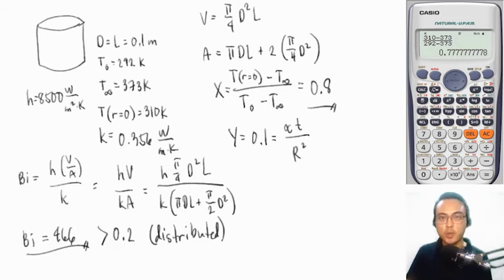In your exams, you have to look for the values of the thermal conductivity, density, and heat capacity of concrete. But for illustration purposes in this example, we have a value of alpha, and that is 5.95 times 10 raised to negative 7 square meter per second. If you substitute everything into our equation of y, we can now solve for the time.